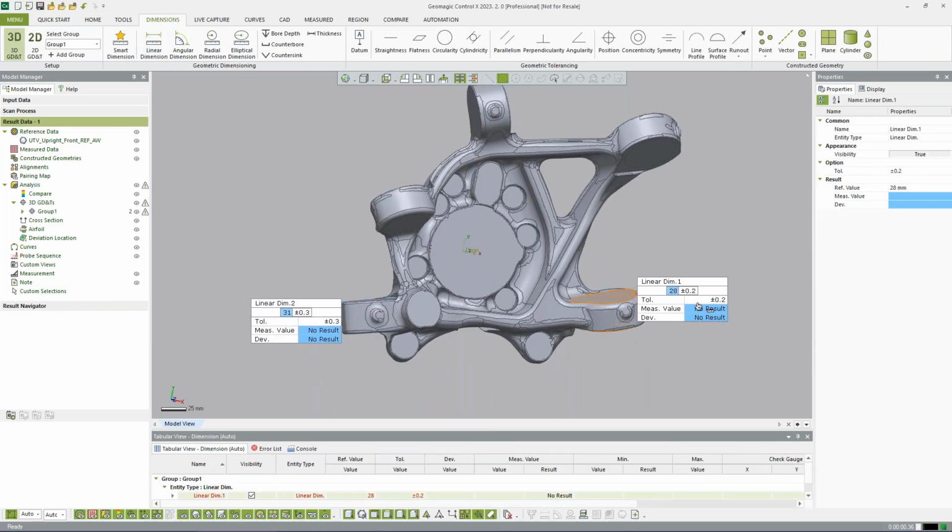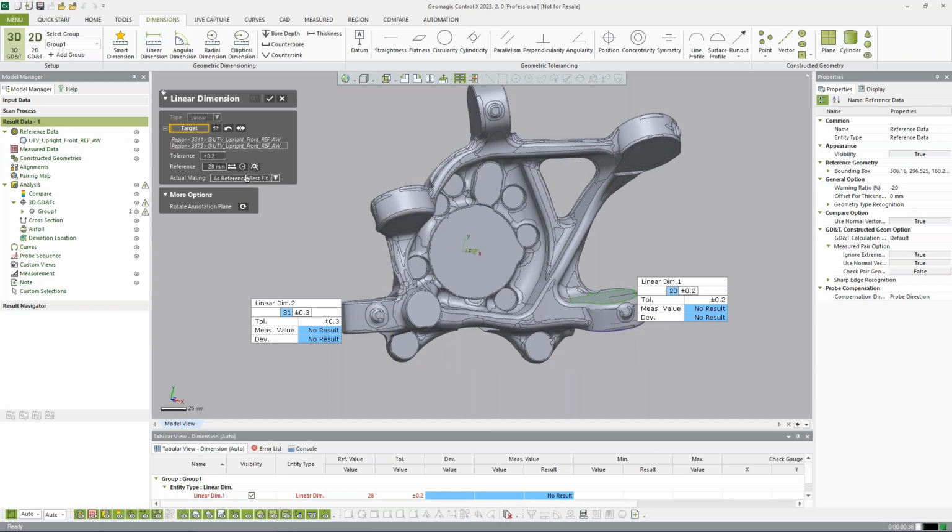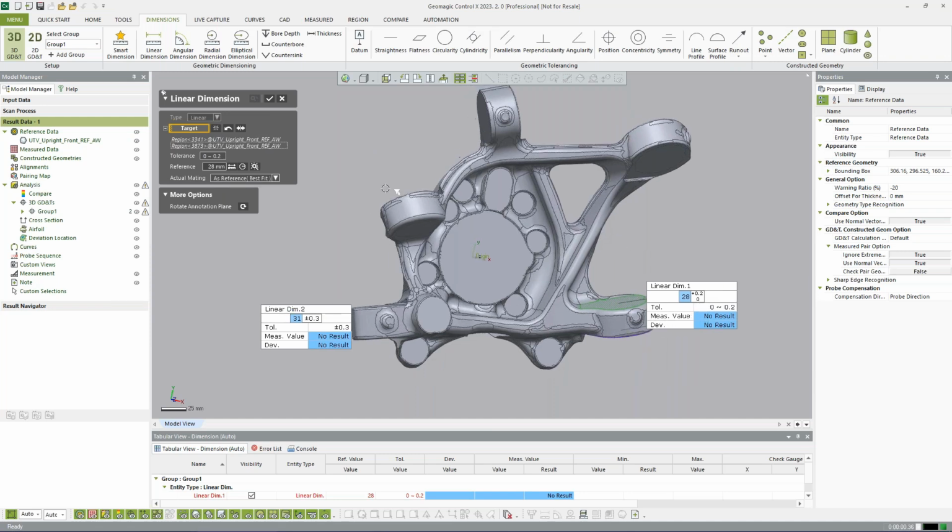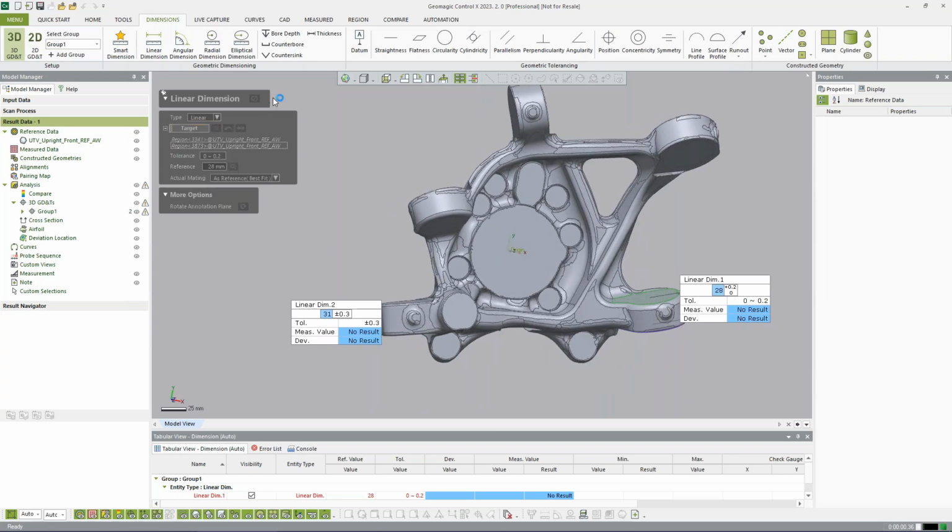The other thing I'd probably want to do on a lot of these cast parts, which I'm not showing right now, is usually do bilateral tolerancing. So normally I'm going to say we want to do minus 0 to positive 2, something like that. Anything undersized from whatever our design spec is we might not want, or there may be a negative small value and a positive big value, because obviously these things need to be beefy enough to hold up.